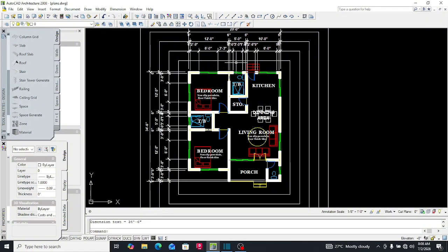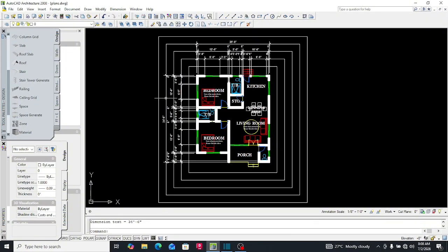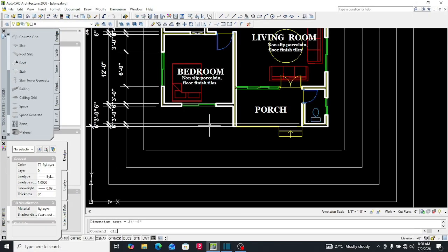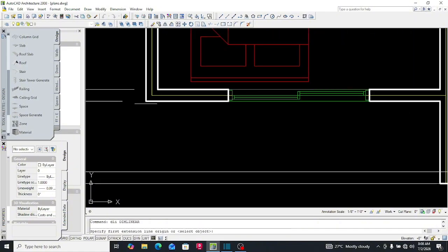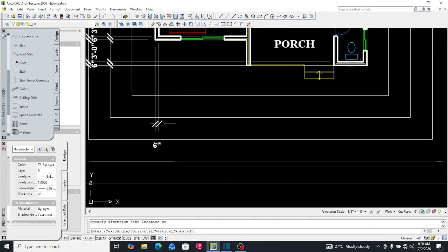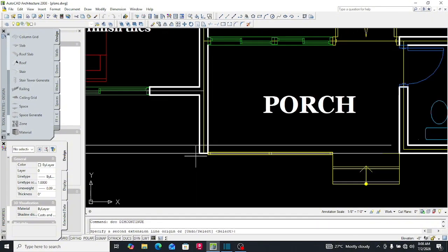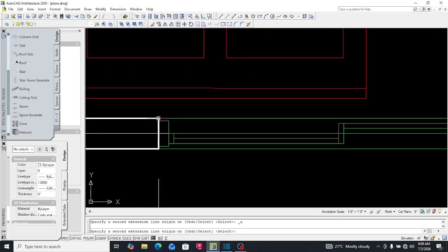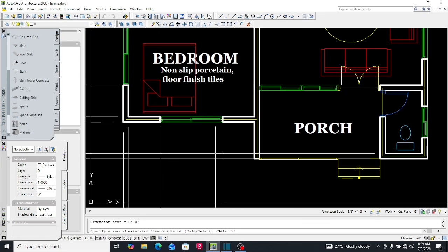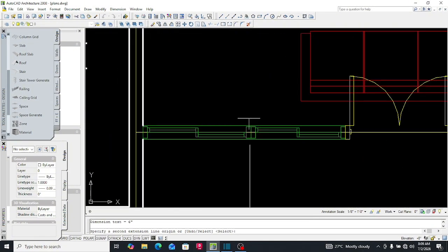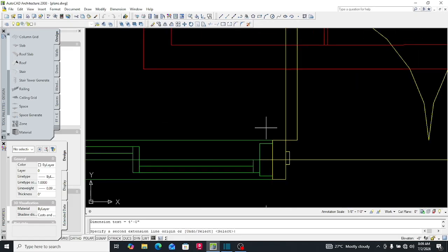We are done with the back elevation. There's the left elevation. Now let's move on to the front elevation. Again, the dimension of the block. Then you pick DCO. Don't forget DCO, that's a shortcut. Then, oh sorry, I have to actually pick the windows. Then come and pick the wall, then a window like this.